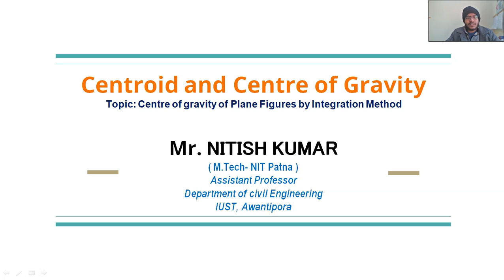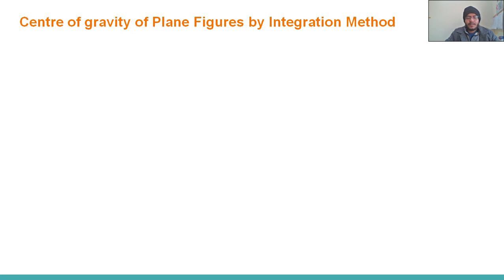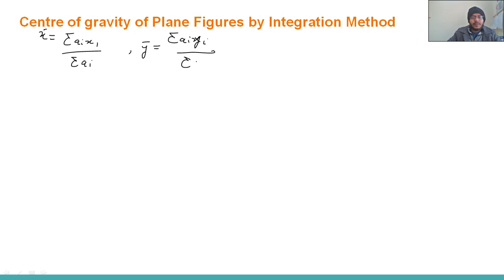In this lecture, I'm going to discuss center of gravity of plane figures by integration method. In the method of moments, I have discussed that x bar would be summation of xi ai divided by summation of ai, and for y bar, summation of ai yi divided by summation of ai.